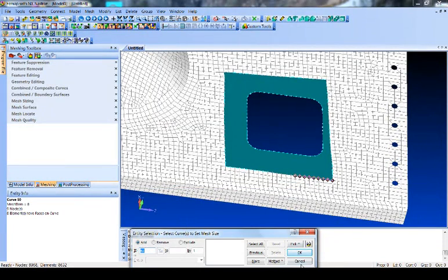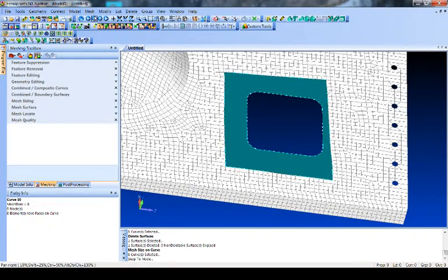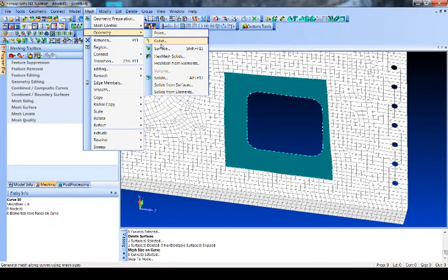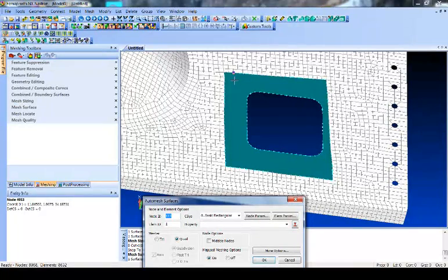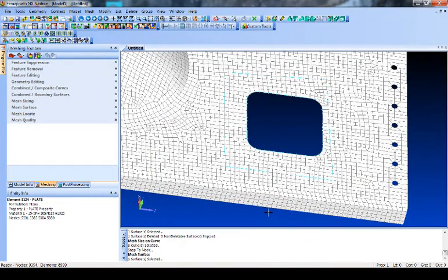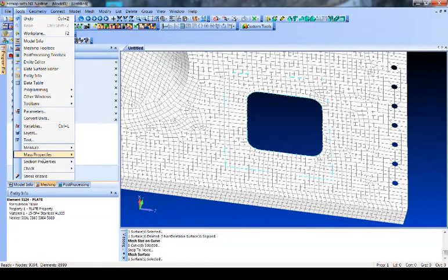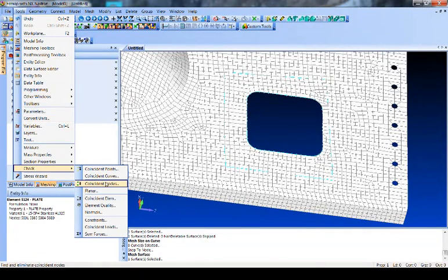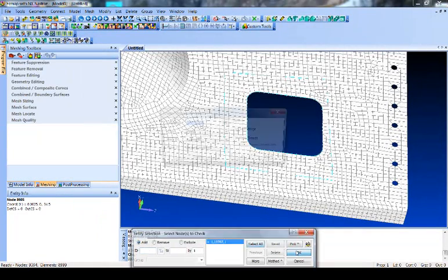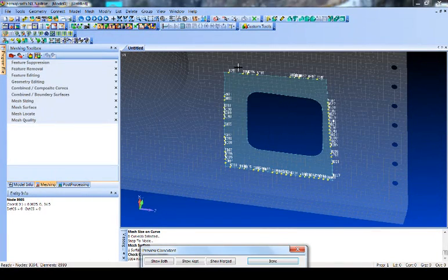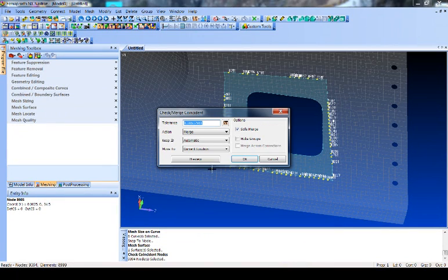So it comes up with roughly the same mesh size, and now we can mesh that surface. It's already got all the sizes set up. We'll set the property, go grab the existing plate, and you'll see now that the cutout's in there. Just to do a quick coincident node check, we'll see that the boundary there has to get merged in. Let's make sure that everything's going to connect.